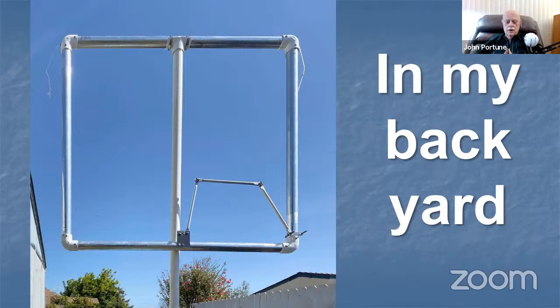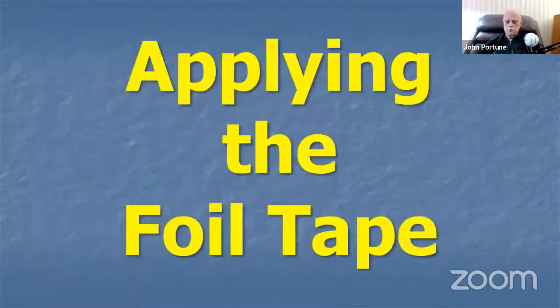Here it is in my backyard. You can see the aluminum foil on the pipes. You can see the corner elbows where you can't see the foil because it's on the inside, but you can see the coupling loop on the right, which is 3 14-inch pieces of 1/2-inch tubing, and the feed point there at the bottom. I don't have the coax on in this particular picture, but it connects to that SO-239 right there on that little square plastic piece at the bottom.